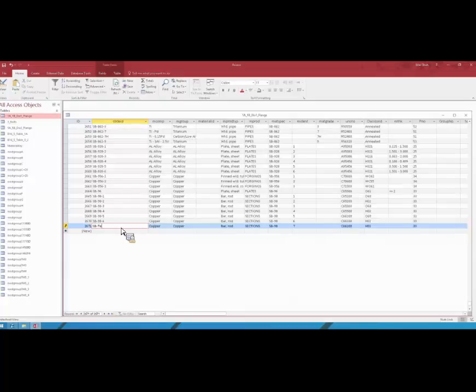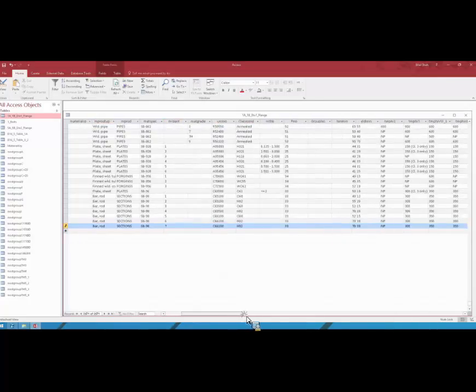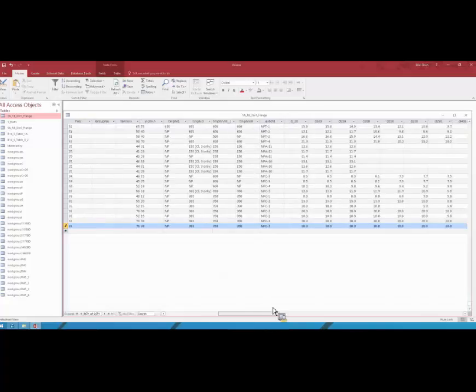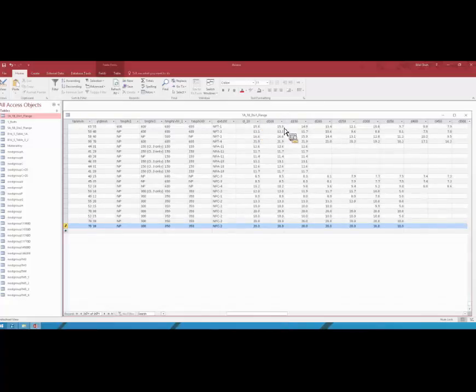For saving time, I've already entered a new flange material by copying the data from the previous record. You can change that by looking at what material it is, what the product type is, whether it is section, plates, or forging, what the material spec is, and then giving the values at different temperatures, like at 20, 100, and 150, and you can change these values.